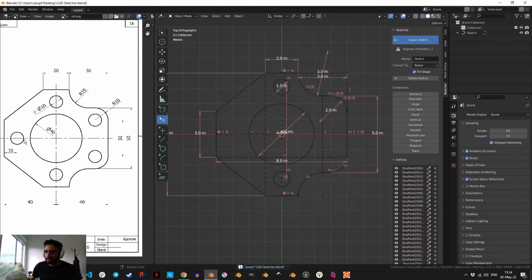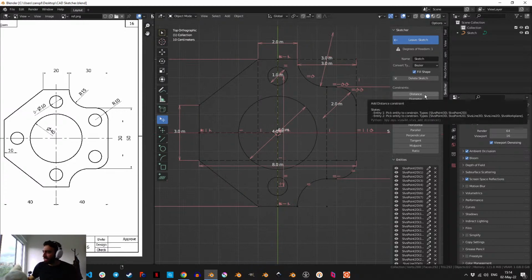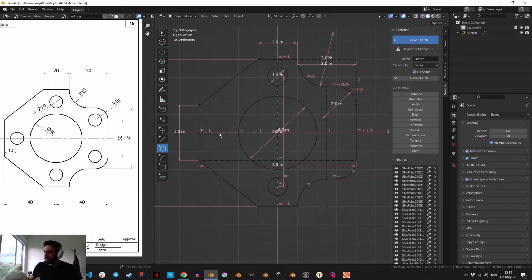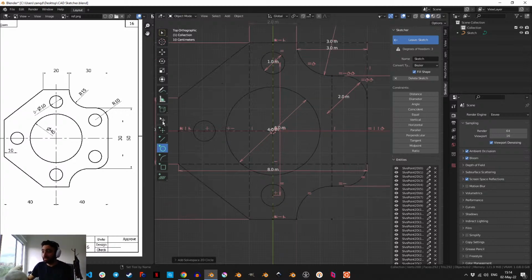And let's create this guy. I'm also going to use the coincident constraint created automatically. If you see this icon, this is the coincident constraint that has been created automatically, which is so cool. And let's make this diameter equal to this.